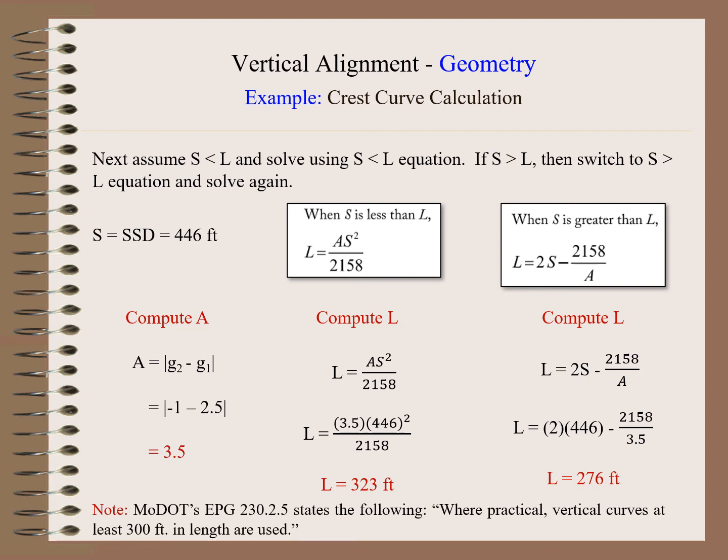Note, though, in MoDOT's EPG 230.2.5 states the following: where practical, vertical curves should be at least 300 feet in length. So in this design example, you would probably bump that length of curve up to 300 feet.